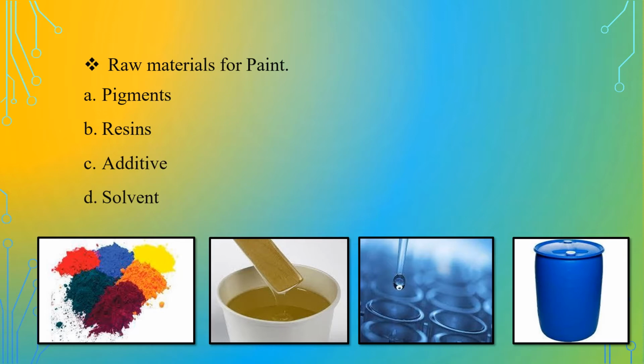Then additives are the materials used to enhance the properties of the coating. They are used in very small quantities to alter the surface properties or rheological properties like viscosity, flow, film formation, and evaporation rate. They are also good dispersion agents.